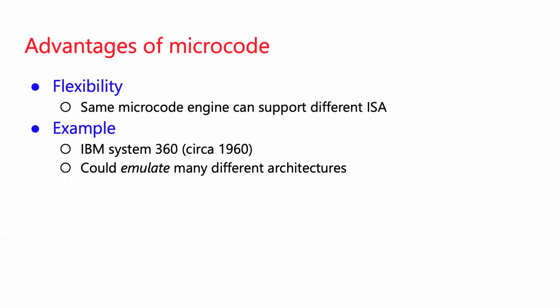So that was our somewhat protracted example of how a lot of more sophisticated operations that the processor could support could be done with the help of microcode, limited or less sophisticated logic hardware, but more steps and even a tiny little internal language in the form of microcode for describing what those steps were.